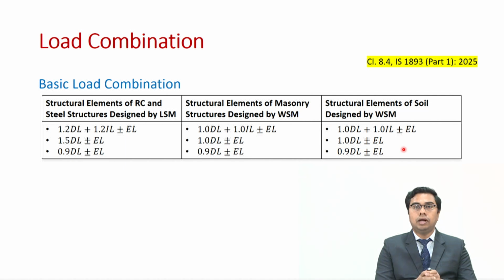Okay. You will find, if you compare, that the value of seismic zone factor has increased, but at the same time now the code gives you relaxation that you do not have to apply any partial safety factor of load when it comes to earthquake load. If you see the load combinations provided in 2016 version of the code, you will find that this load combination is given as 1.2 times of dead load plus imposed load plus minus earthquake load, all in the bracket. So, every load was multiplied with 1.2, and similarly in the other cases as well. So, that is the relaxation that code has now given. So, you increase your design seismic load, but you need to check your building design for slightly relaxed load combinations.